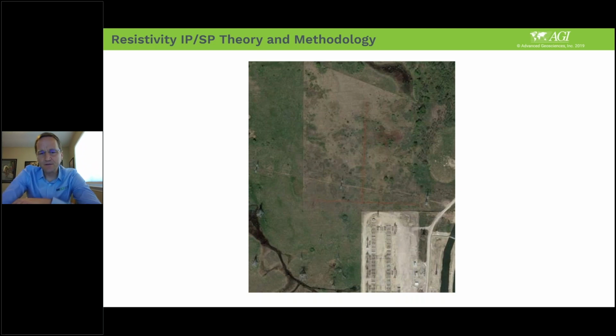So in getting into line placement, this is a power substation, and there's a high voltage overhead line going like this from left to right. The client asked the consultant to run 2 Wenner arrays, and there are these red lines you can probably barely see. One of them goes directly under the power lines and one goes parallel. They were hoping that both of these would be similar Wenner soundings, and they were not.